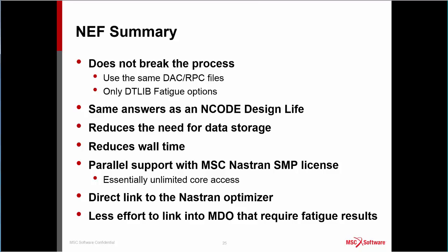We've got the direct link to the Nastran optimizer. And if you're doing an MDO where you're using, let's say, modeFRONTIER, and you have a separate Nastran and then fatigue analysis as two different inputs, we can now merge those into one. You only have one thing to execute, and it's faster, so your overall MDO will run much faster.